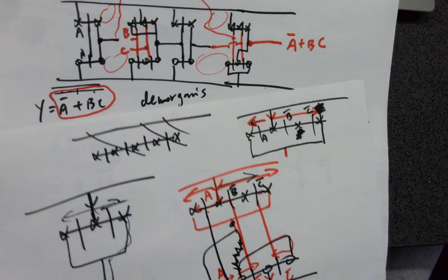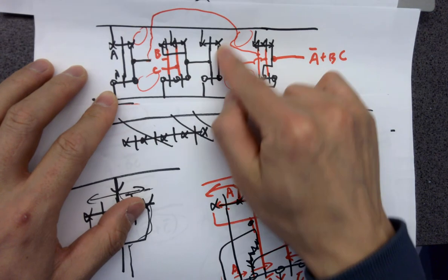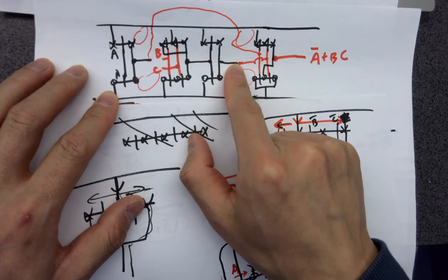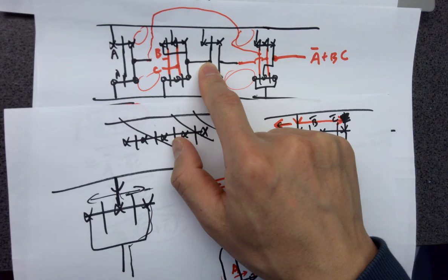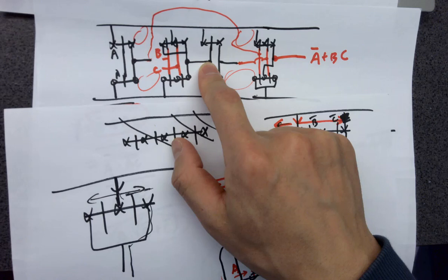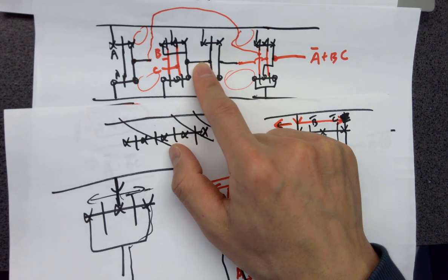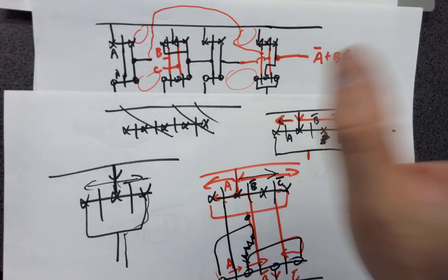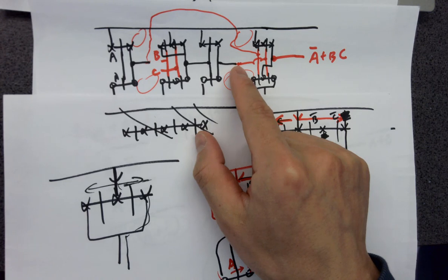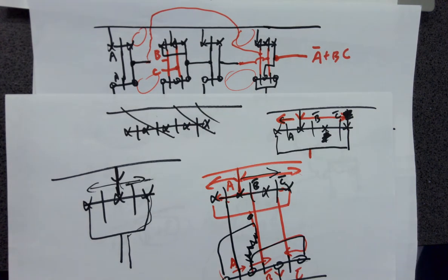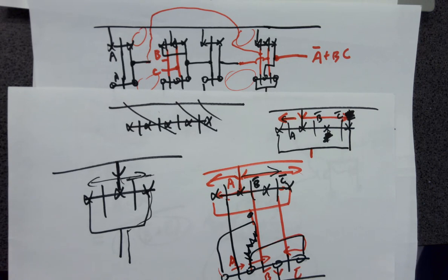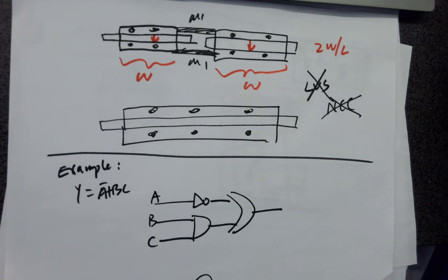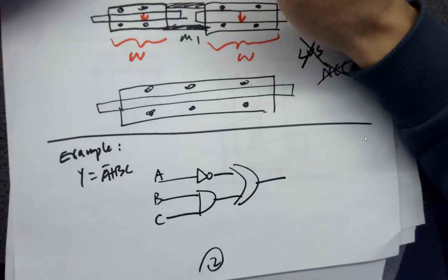But I can imagine if you have, that's not a good example. I think the main thing is if you have separate gates, there is a lot of space in the middle to have all the vias, and because poly are gates and inputs are polys, you have to drill a hole to the metal one layer using a via, right? So in that case, it has a lot of space because the design rules require that kind of spacing. So it results in a lot of empty space in the middle. Okay, that's the main downside of it. So there will be an example for the slider, and you can compare the total layout area really easily.